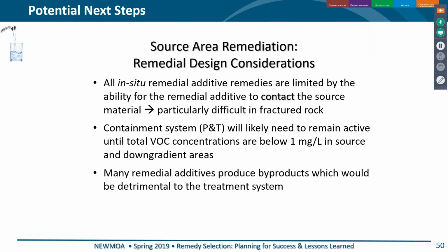that something might be. Any in situ remedy is limited to contact. You've got to have contact. Very difficult to achieve contact in fractured rock. The other thing is, the containment system is probably going to have to be a part of any remedy. You can't just shut it off and let the water supply get contaminated while you're worrying about getting rid of the DNAPL and probably maybe increasing TCE concentrations by what you're doing. And also, you have to keep the pump and treat system operating.